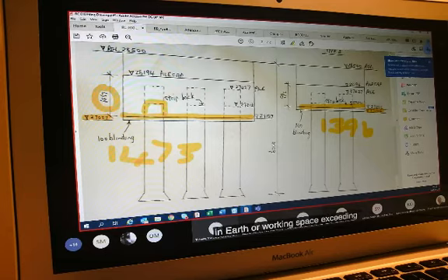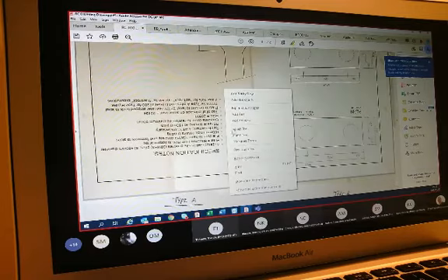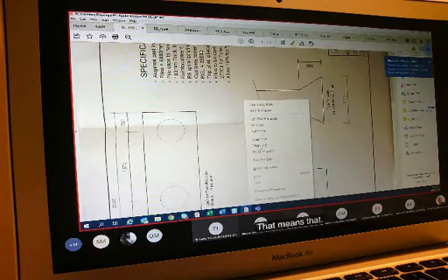And in measuring that, we would also look at back excavation of the vertical sides of the excavation in earth for working space exceeding 500 and not exceeding 1 meter 500 deep, for placing and removing the formwork to the sides of the pile caps flush against the excavated face.